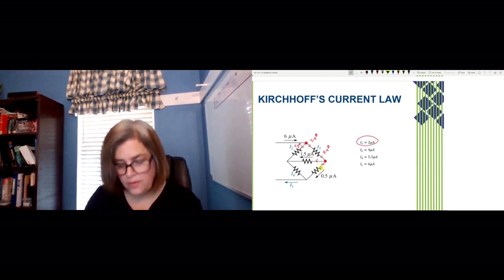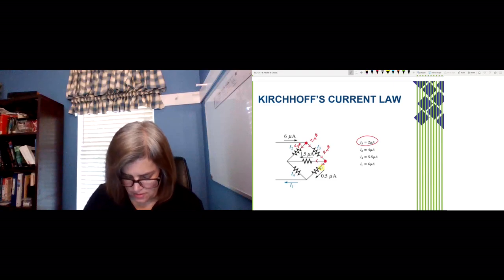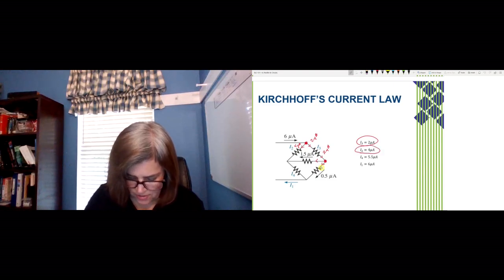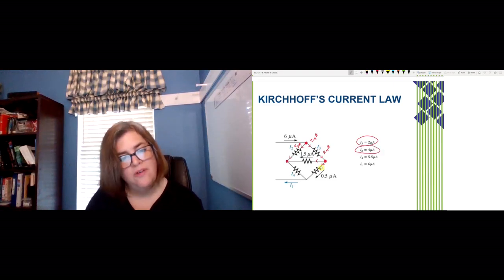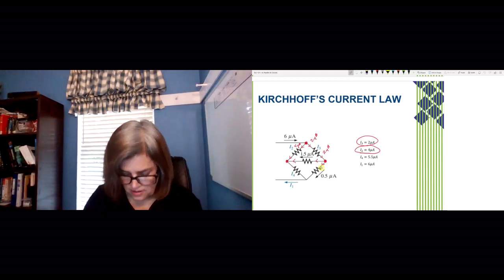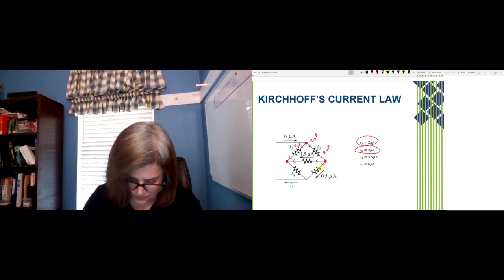So we've got 4 microamps there. If we look right here, we've got 4 microamps coming in and 1.5 microamps coming in. So I4 must be 5.5 microamps.